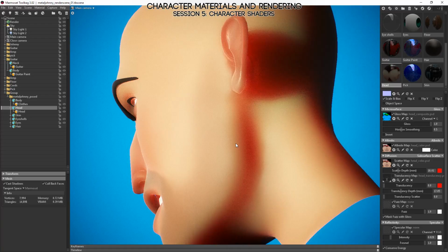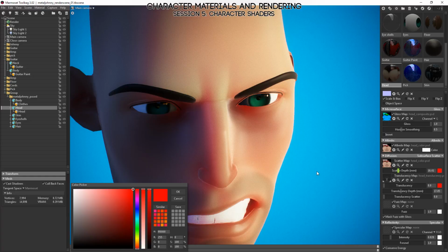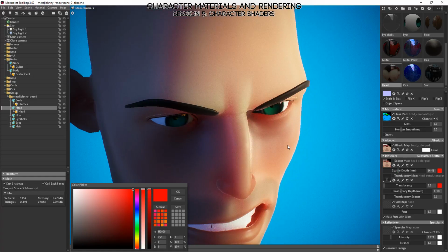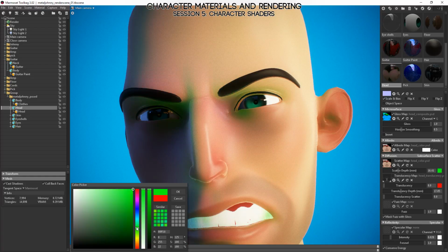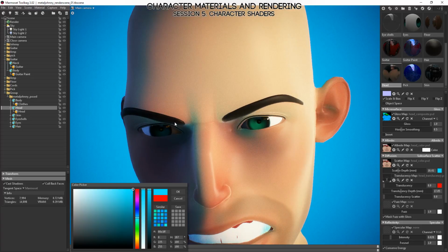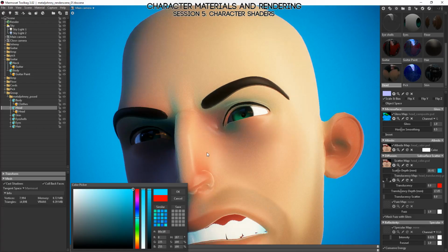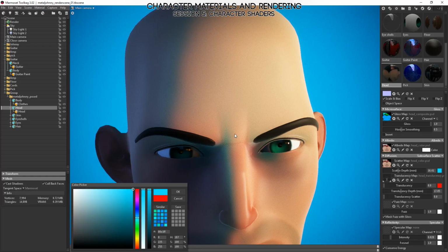So if you ever run into situations where a nice subsurface scattering color that you think is going to look right ends up looking bizarre, this is probably why it's happening. So you can see similar behavior happening with different subsurface scattering colors. As I change this to, say, a cyan color, the translucency along these edges starts to look more cyan. However, stuff that's right next to it takes on a warmer cast simply because there is less cyan bouncing out back in this direction.